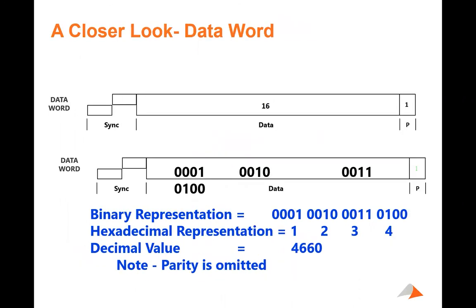Okay, the data word. And it's just that. It's 16 data bits. You can look at a data word in a decimal value, or you can look at a data word in the hex value. A lot of people, as they get used to seeing what data should be related to what kind of message and what subaddress, are just reading hex all the time.